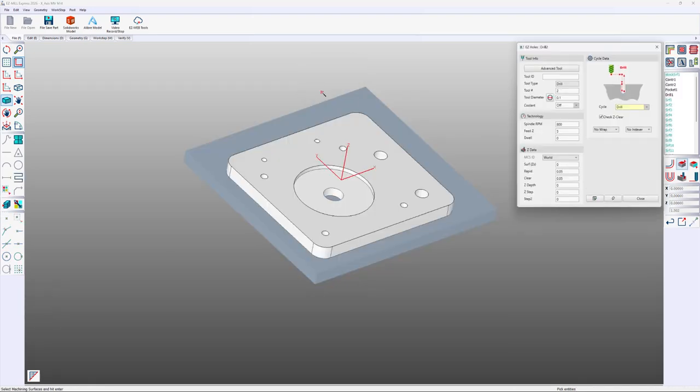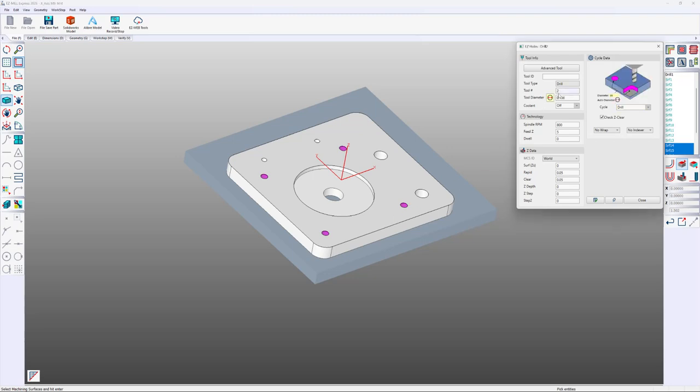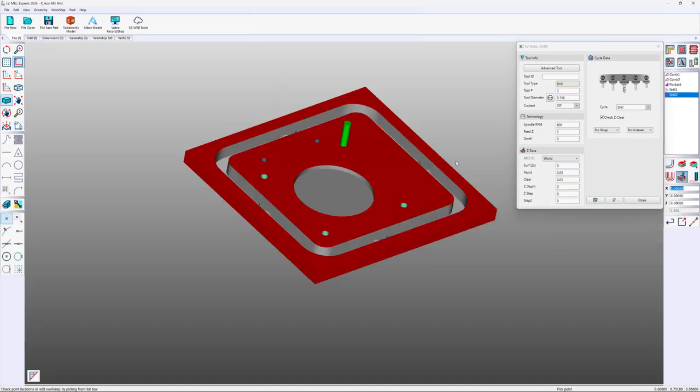Create a second drill operation. We'll use these holes. There's 4 of them. Calculate diameter. Tool number 3. Now as you can see, there's a change in color. For each tool, EasyCam changed the color in simulation. It helps you to keep track of what's machining what.